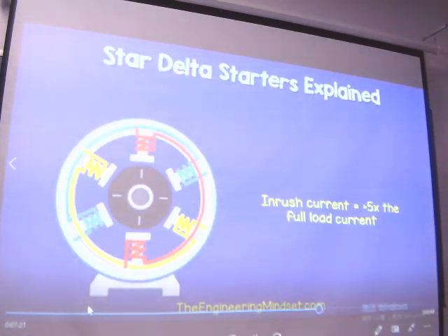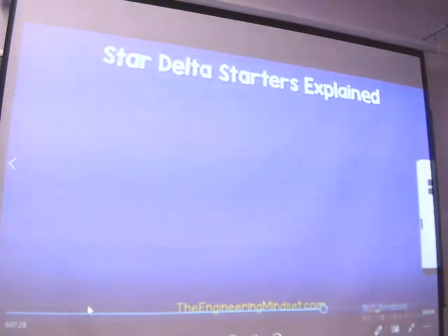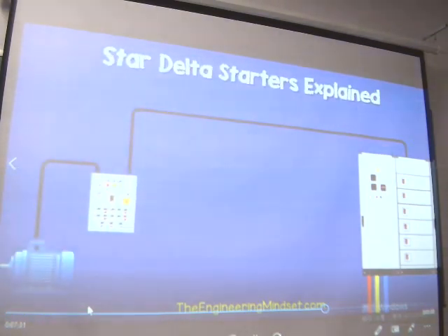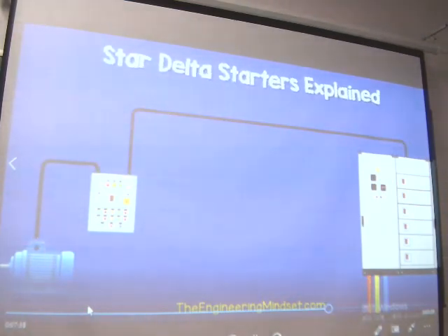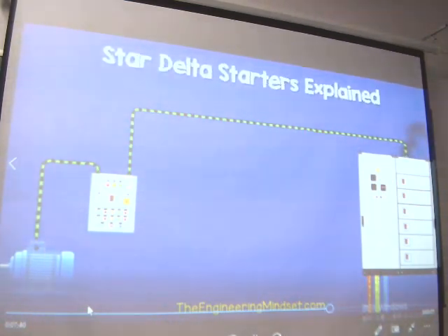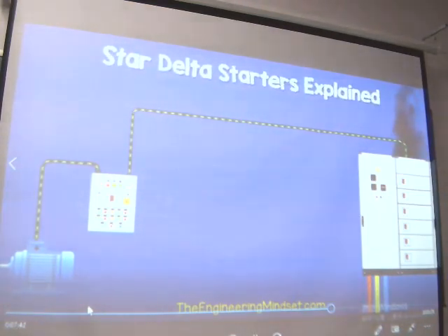When a large induction motor starts in delta, their starting current can be over 5 times higher than the full load current, which occurs when the motor stabilizes and runs normally. This huge surge in current will cause lots of problems. The building's electrical system will be hit by this sudden large demand. The electrical infrastructure will rapidly increase in temperature, leading to component failure and even electrical fires.